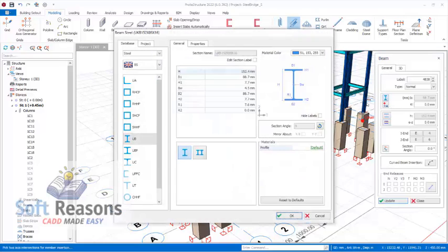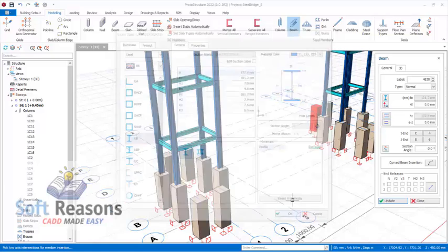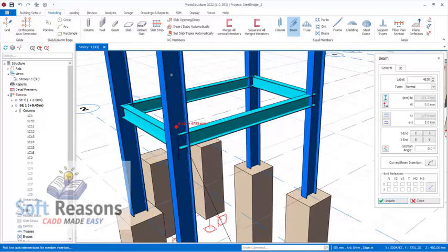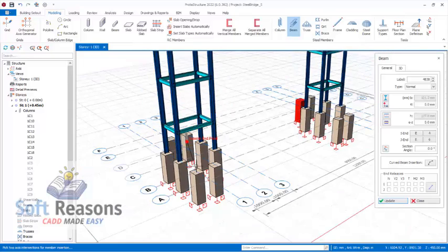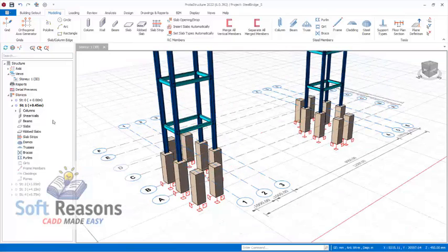Alright, so we still get to the beams. Okay, this time around, let's check the sections. We use this one, 178, 102, 19 thickness. Select that. So we pick the first point and connect it to. Okay, escape that, close this first and navigate to story 2 right there.